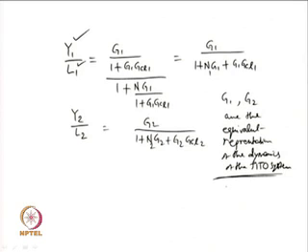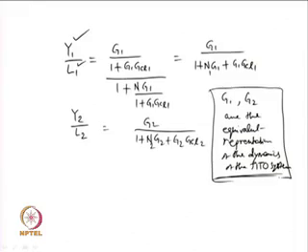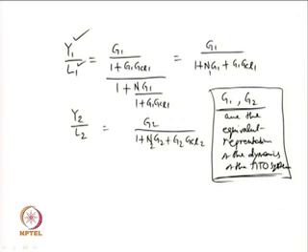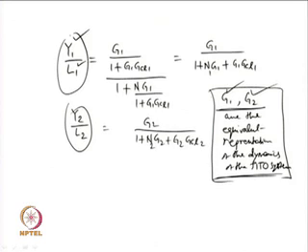When the TITO system is decoupled, obviously we get the equivalent representation of the whole TITO system dynamics in the form of G1 and G2. That means, as if we have got two single input single output systems G1(s) and G2(s). Corresponding to that, the transfer function between the output and load disturbances can be expressed in this form.